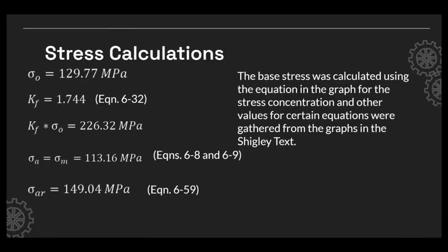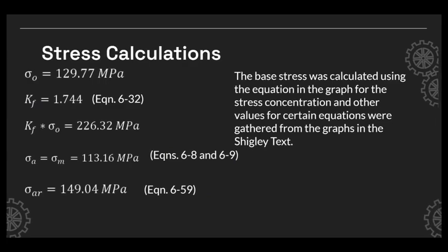In this analysis, we needed to calculate a stress concentration factor and a number of stress values. The stress values shown were calculated using equations and graphs from the Shigley text. These values are used to calculate fatigue factor of safety and the number of cycles before failure.